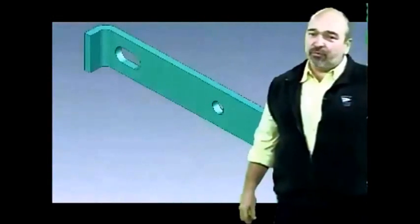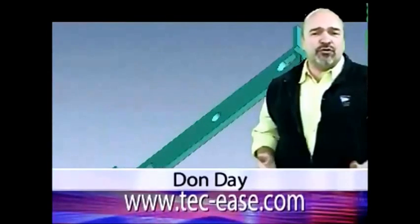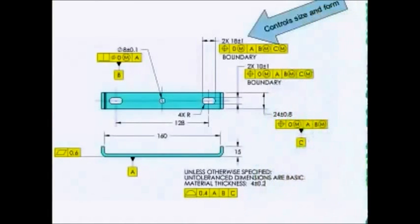Controlling slots and other irregular shapes has always been a challenge. The standard gives us two ways to tolerance slots. The first works for slots only. The length and width of the slot are toleranced as two features of size.